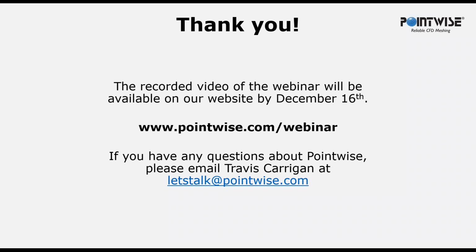All right, can you delay the regeneration of the surface mesh so you don't have to wait every time you change a spacing constraint? Okay, so this is a great question in terms of productivity, and I have experienced the same thing, and there's a good approach to use in this situation. So as you probably know, there are 2 ways you can change a spacing constraint. You can select it in the GUI and then go to the toolbar and type in the spacing constraint there and change it.